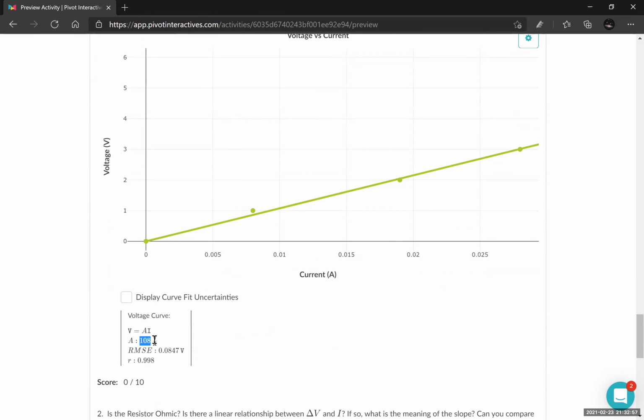If you scroll down, you look at the resistance that we got, which is the slope of this line. So I got 108. Not that close, but remember, I didn't take enough data points. If you get all 10 or more data points, you can get a closer value. Generally, the more data points you have, the better the experimental result. You can do half a volt increments instead of 1 volt, so then you get like 20 data points. But this should be enough. If you take 10 data points, you should get a value much closer to the actual value of the resistance.